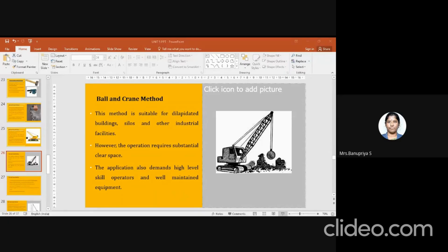When the slurry is injected at high pressure, cracks will form on the surface of the particular component. When you make a hole and apply high pressure, it will burst. So before the bursting, they form cracks on the surface of the component. If you are going to demolish a floor, first you clean the floor and then drill holes at equal intervals.